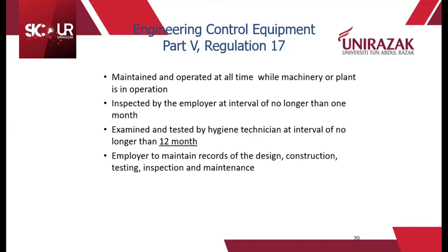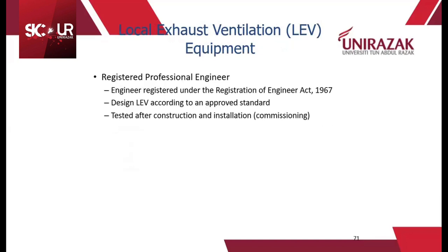Employer to maintain record of the design, construction and testing, inspection and maintenance. LEV equipment registered by professional engineer. So engineer registered under the Registration of Engineer Act 1967, design LEV according to an approved standard, tested after the construction and installation commissioning lah.